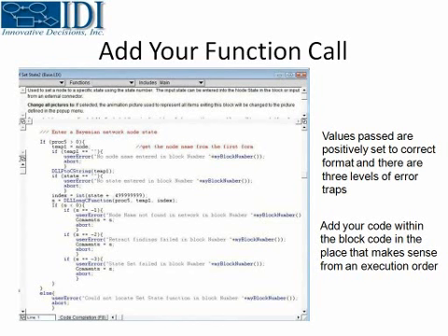So in this particular case, if it's greater than 0, I'm going to execute the code. But if it's less than 0, if you look at the bottom of the screen, it's going to say cannot locate the set state function in my block, and abort. So just like with normal ExtendSim, it'll stop the program, pop up with that error message, and tell you that it couldn't find this particular function in the library.